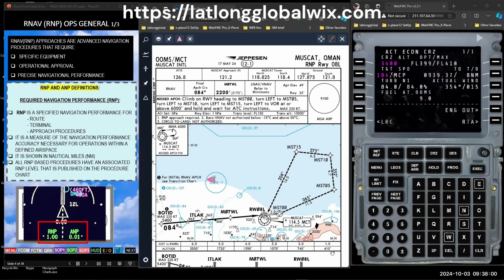What we'll do shortly is we'll configure for flaps 5, because I'm by myself on the flight deck, and then turn to left base. Generally, you would configure to flaps 5 when on base leg. So we'll go into the simulator and view just what I've been speaking about.